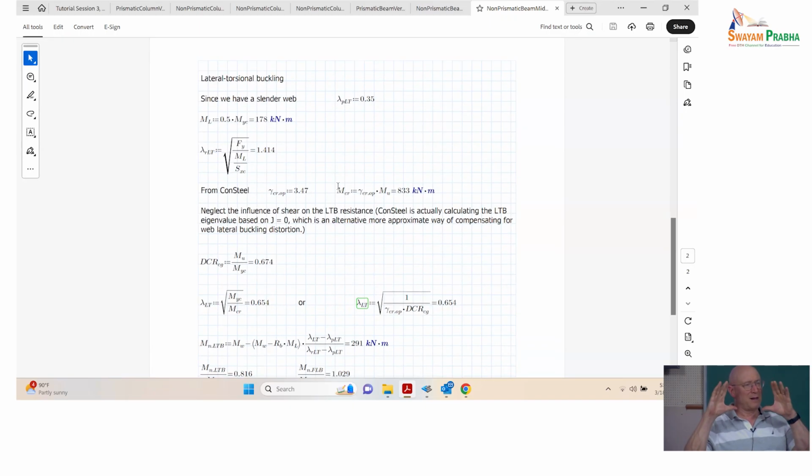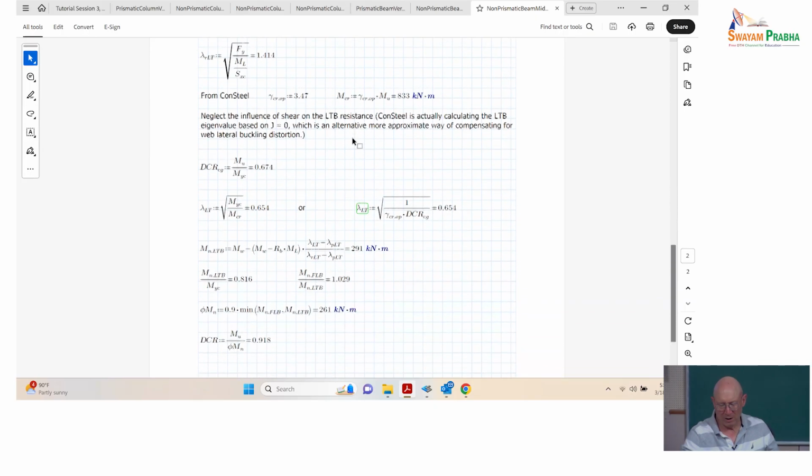The simplest way to put it here, I want to check the strength of an equivalent prismatic beam that has the same Mu to Mw, if you wish, as this cross section, and has the same gamma critical. And so that prismatic beam is now a surrogate for checking where am I here at this middle cross section. Just did the same thing for the top. Obviously, if we go at the bottom, the moment is 0 at the bottom, so there's no need to check the bottom, right? So that's all this is doing.